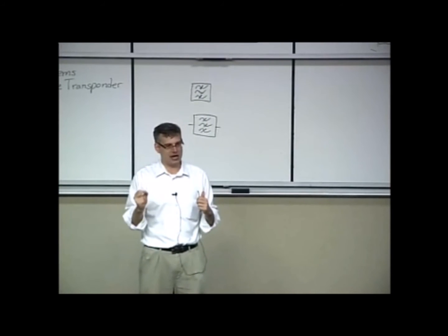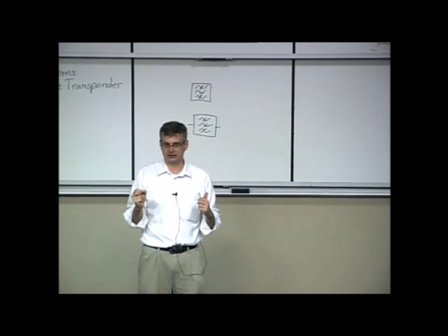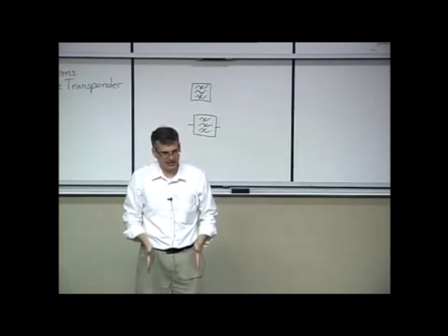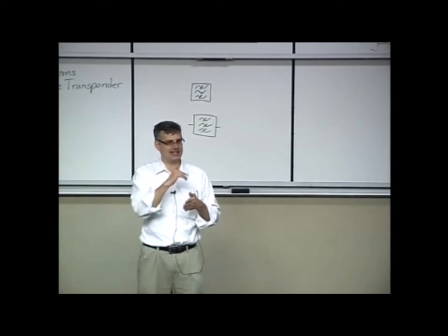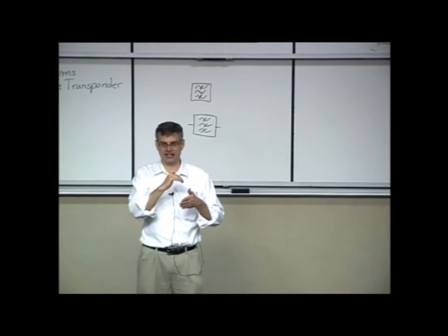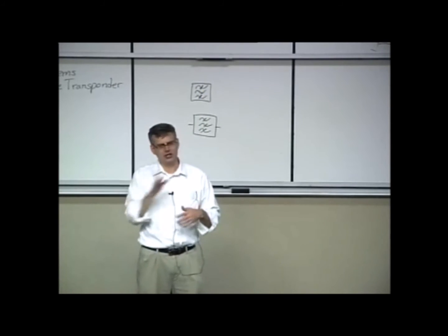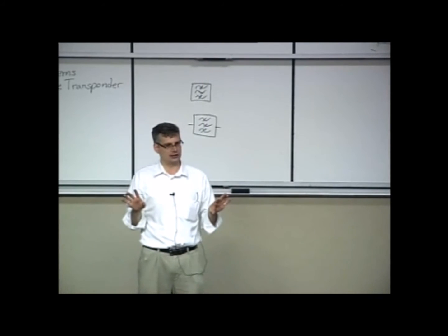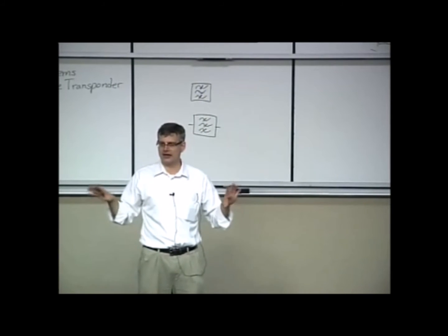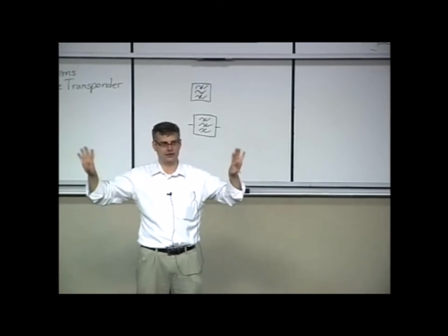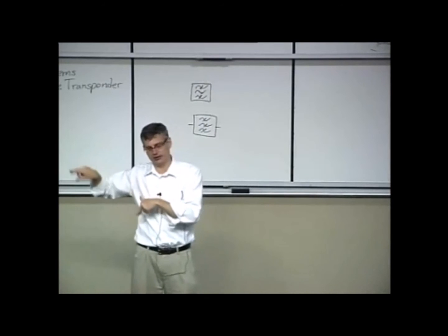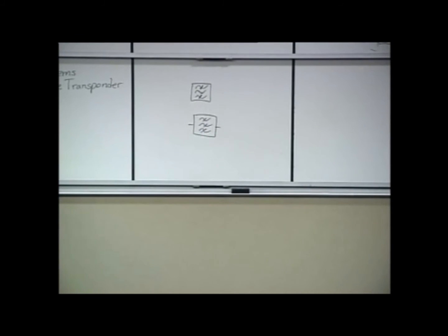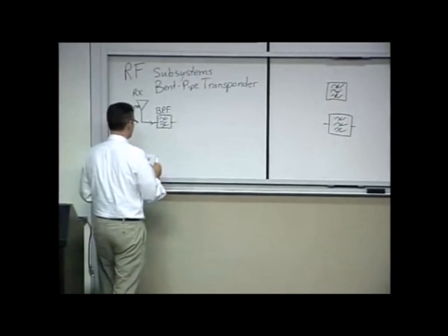To make a really tight filter in electrical engineering, something that has extremely tight stop frequencies, implies that you may need to add loss in order for that to happen, which you don't want to do at this point in your chain. You just want a little bit of filter, because all you're really doing at this point is trying to bang down any really strong close-band, out-of-band interferers that might be leaking through your radio chain. Worry about the really tight filtering later in the process. You'll see where that occurs. That's just a little tidbit for RF engineers out there.